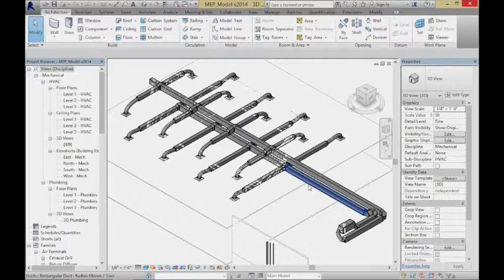The other thing you have to watch out for with ducts is that every time you put a bend in a duct, it loses some efficiency. If I'm looking at it in plan, running the duct straight through to the terminus over here is very efficient. If from here I have to have a bend up here, a bend over there, and come back here, at each one of those bends I'm losing a lot of efficiency. It just takes more energy to move things around.